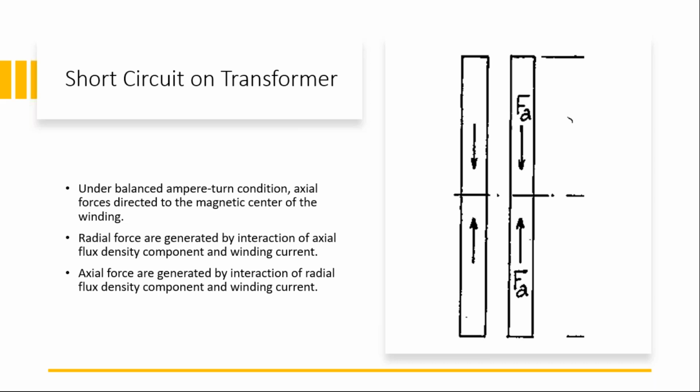So what are some of the design considerations you want to incorporate to make that happen? Can you talk about that? Yes. So when it comes to the winding construction, we have a design, and we will have winding height. Say, for example, LV is at 50 inch height, and HV is at, say, 49.75 or 49.875 height.